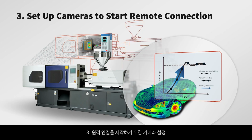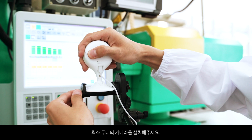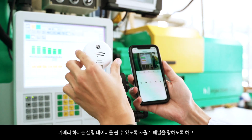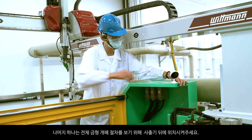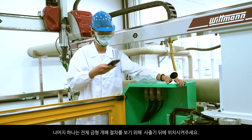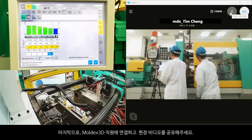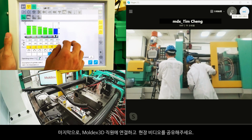3. Set up cameras to start remote connection. Set up at least 2 cameras. One faces the injection machine panel to see the experimental data. The other is placed above the injection machine to see the complete mold opening and closing procedure. Finally, connect to Moldex3D personnel and share on-site video.